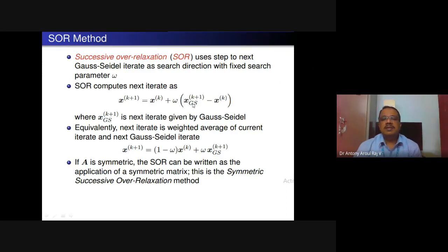So the latest value is 31 and this is 30. The difference is 1, and this is again 30. So now this is 0.1. The under relaxation factor is 0.1. So in the next value, I will not be giving 31, I will be getting 30.1. You may ask why I have to do it like that.